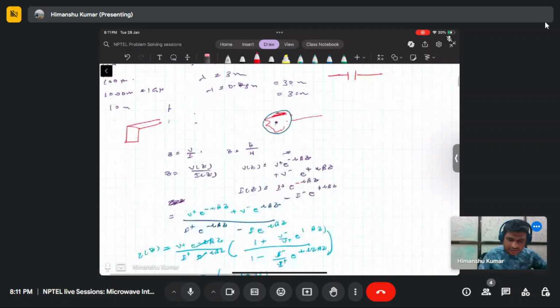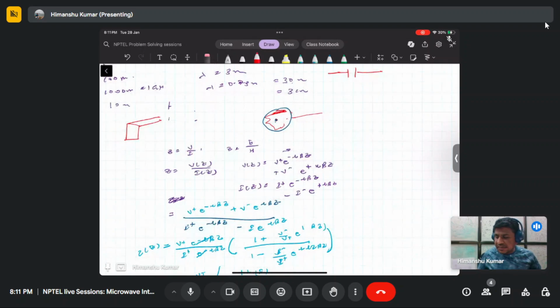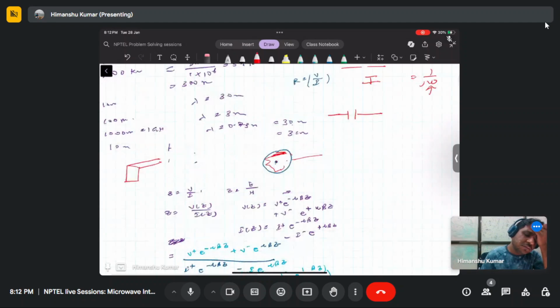So if you start deriving the transmission line equation, if your wavelength is very large, those will become independent of space. That's why you don't need to consider the distributed capacitance and inductance in that case. Does that answer your question?